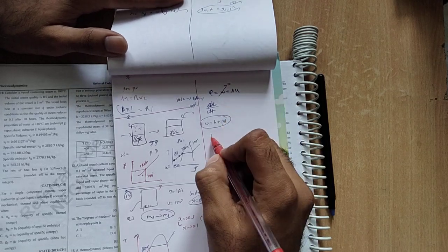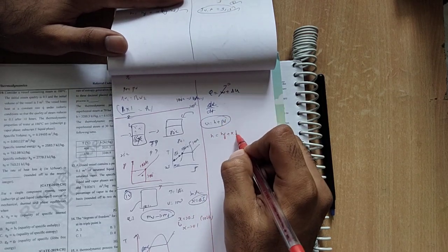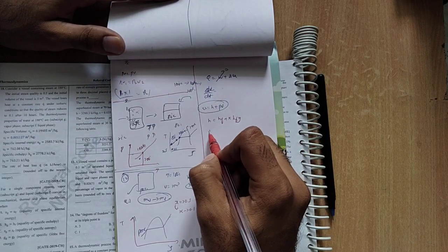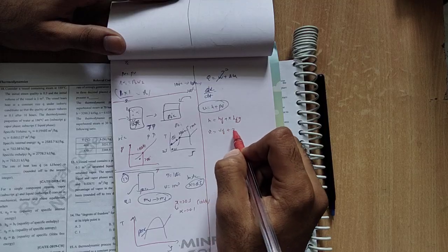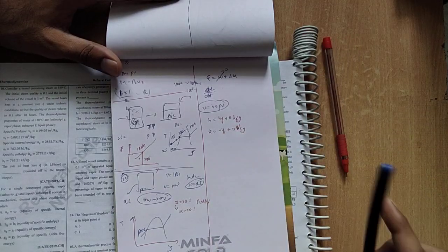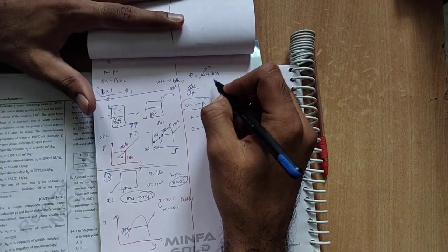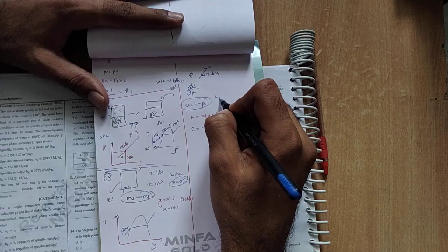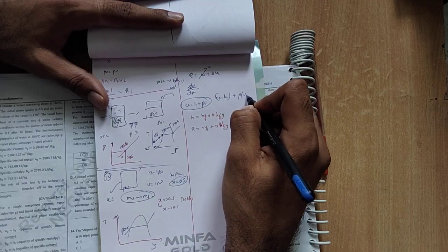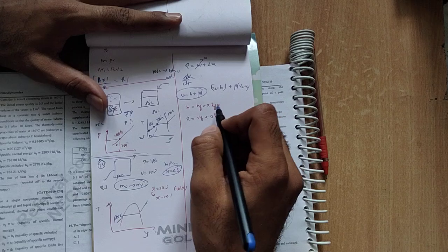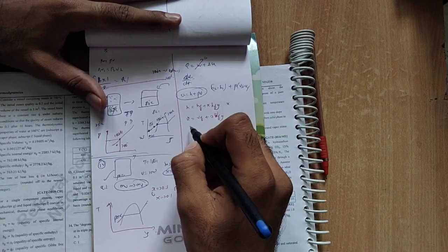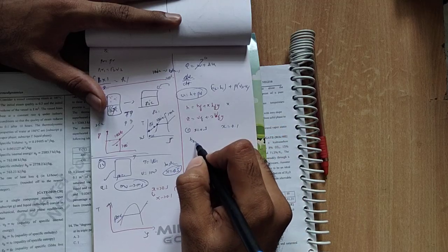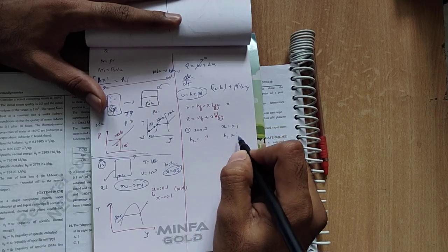In my point of view, h equal to h_f plus x h_fg, and this pressure is constant. So v equal to v_f plus x v_fg. But yes, I think so, guys, the change of enthalpy is h2 minus h1 plus P times v2 minus v1. For this entire thing, one case is x equal to 0.5, another case x equal to 0.1. First calculate h2, how much, and calculate h1. Later you just subtract.